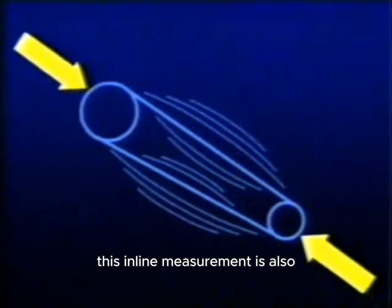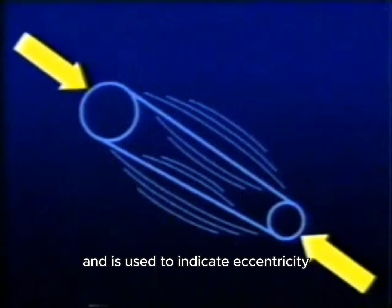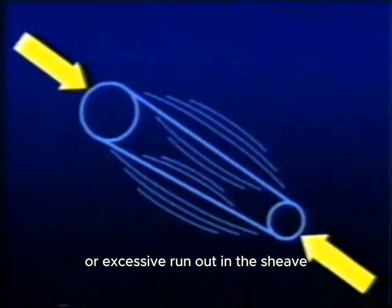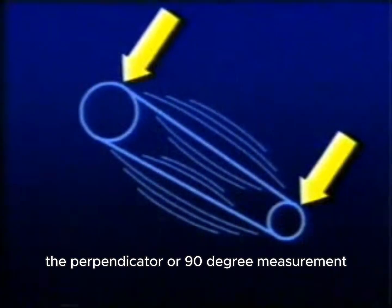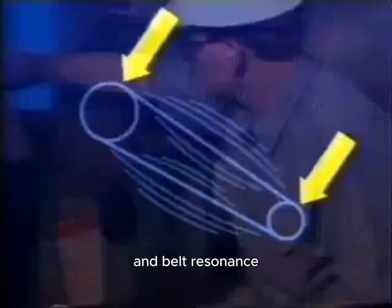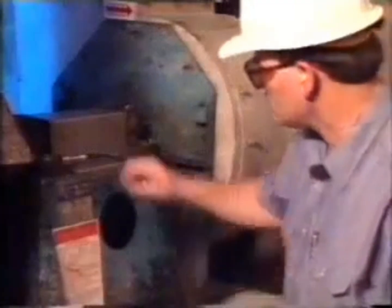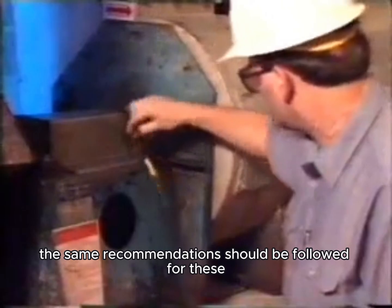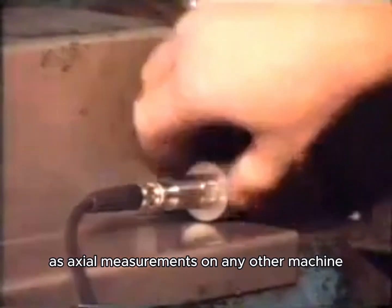This inline measurement is also the direction of belt tension and is used to indicate eccentricity or excessive runout in the sheave as well as a bent shaft. The perpendicular or 90-degree measurement better determines sheave misalignment and belt resonance. It is important to acquire good axial measurements to confirm misaligned or bent sheaves. The same recommendations should be followed for these axial measurements as axial measurements on any other machine.